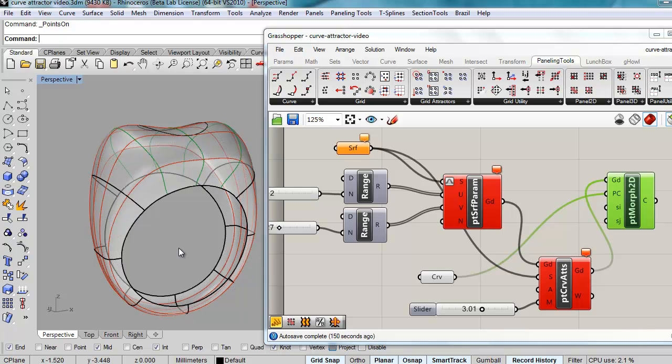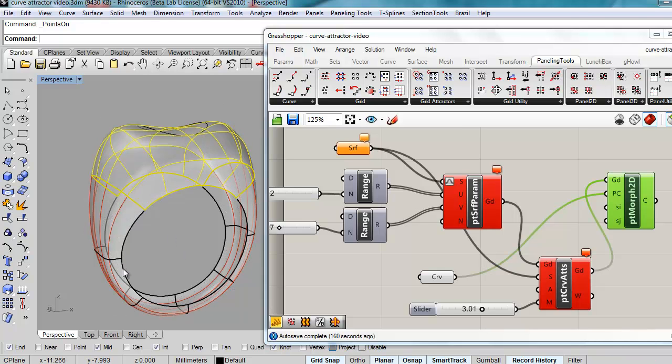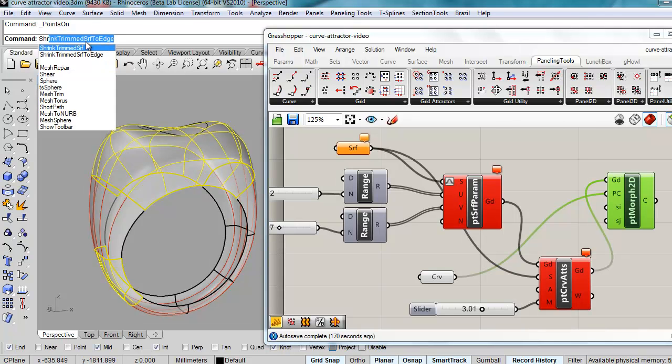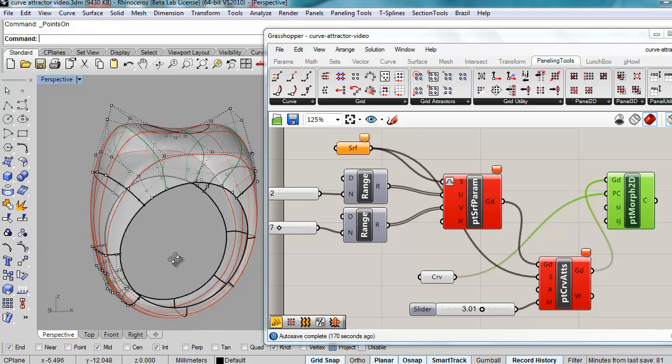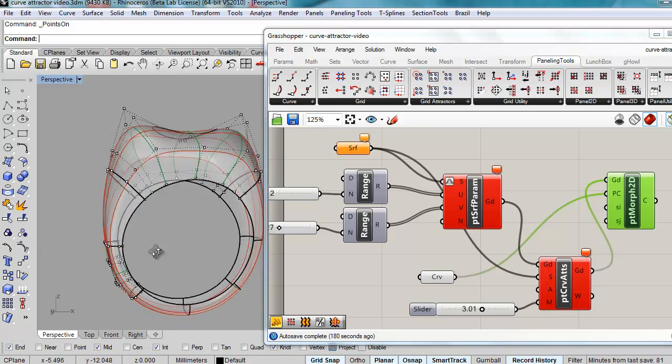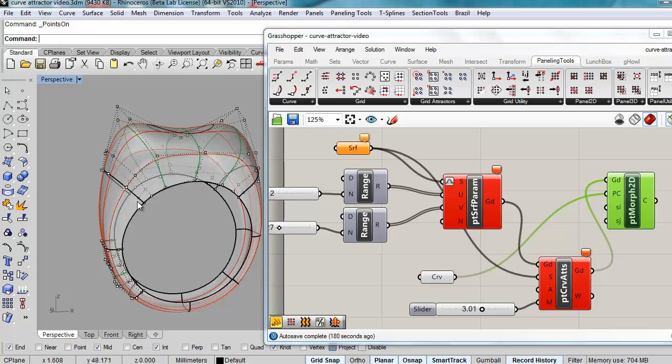If you really want to shrink the surfaces to the size they are right now, you have to use the shrink command. That's what I did. And now if you look at the control points, you see that they are shrunk to the actual size of the surface. You do this shrinking by isoparm. That's really important in order for this command to take the effect we're looking for.